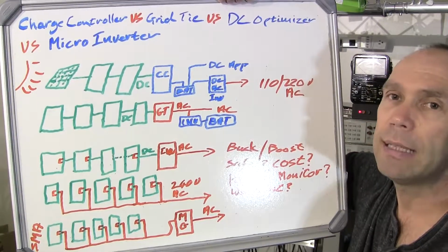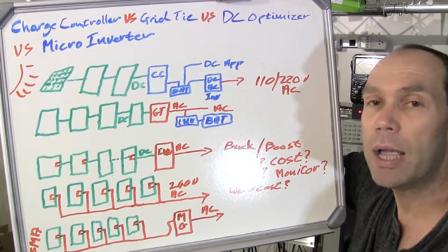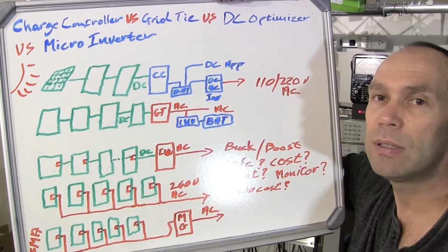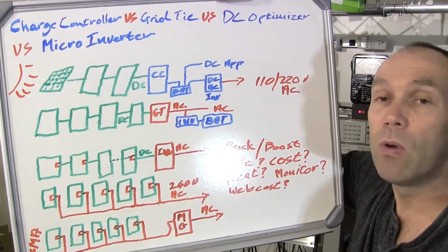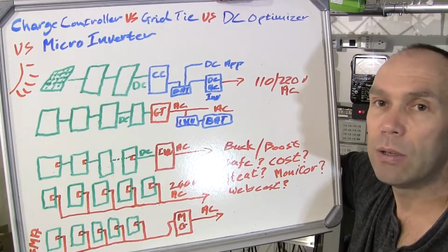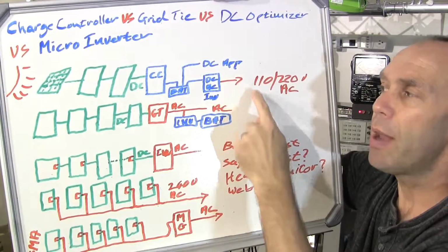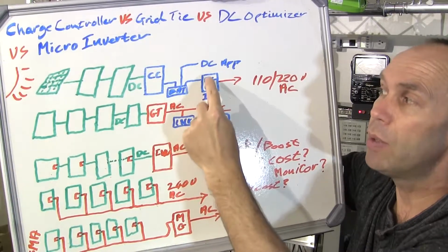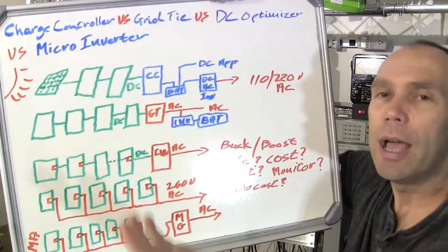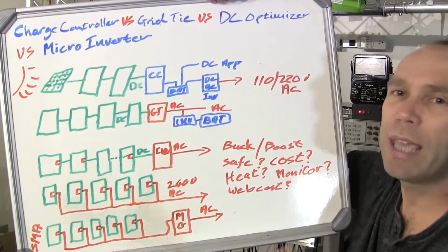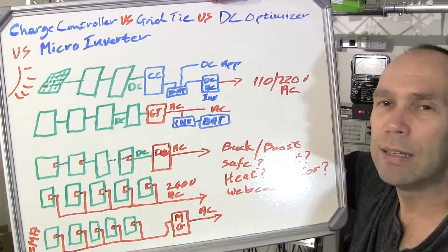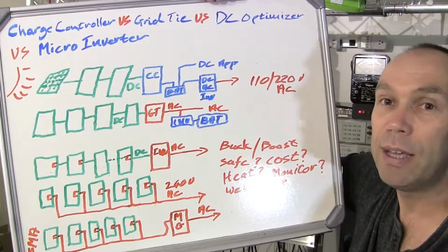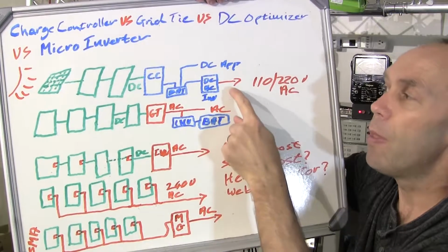Your standard lead acid batteries tend to have a reasonably high internal resistance. Lead crystal batteries have a lower internal resistance, and the best battery technology for low internal resistance are your lithium technologies at the moment. But if you need to run AC applications, then you may have to draw the DC out of your battery and go into a DC to AC inverter. And in a log cabin, you may be in a situation where you cannot have all your appliances run off DC. You know, some folks these days obviously want a big screen TV, it's AC, so that's where you'd need that inversion.